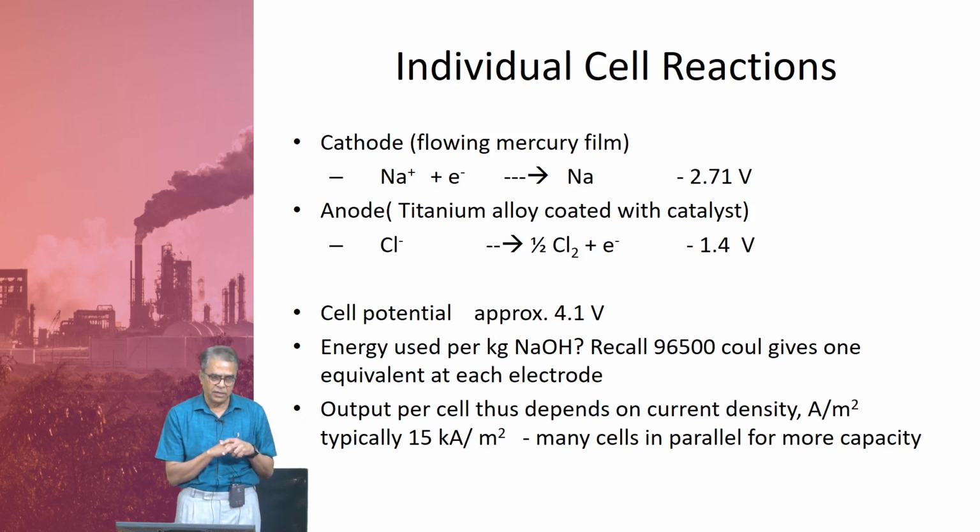Now come to the second electrode, a similar reaction I have put in there. Now, totalled up, you get this reaction of NaCl splitting into Na and Cl, and the voltage is 4.1. Which means you cannot have a mercury cell which operates at anything less than 4 volts and still hope that there will be production. So, we have got one good learning by just studying the process.